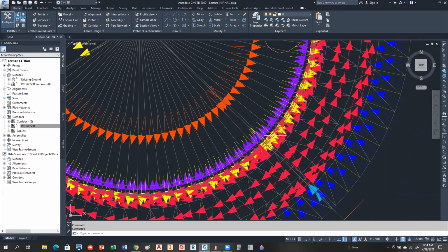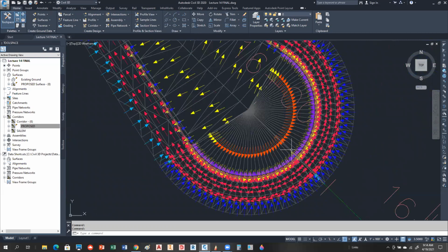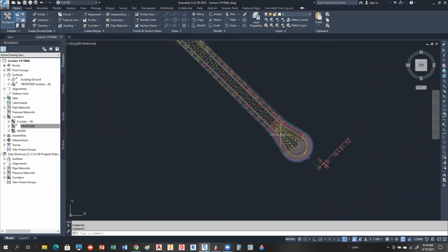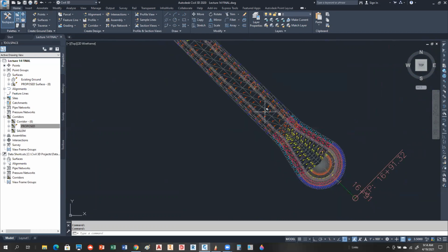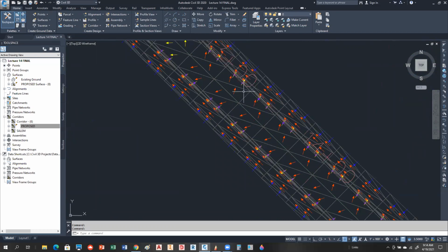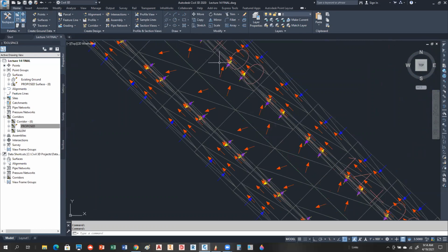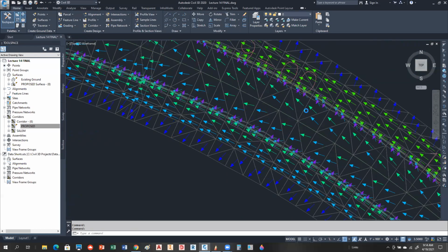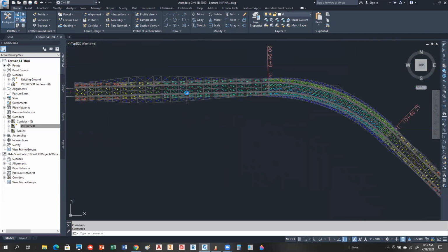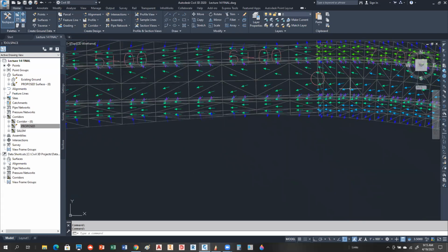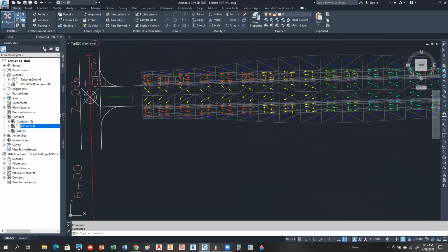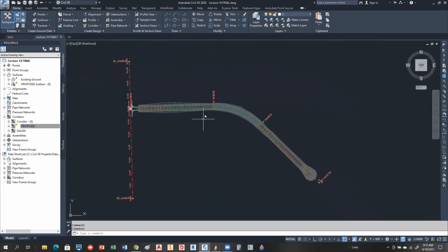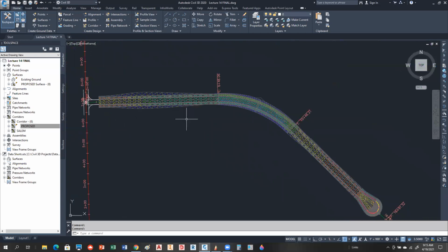If you've ever driven in cul-de-sacs, you'll notice there's usually a catch basin at the end of it, unless it's just draining a different direction. So, if that thing's high up, it might be draining out. But notice the rest of this thing is pretty much primarily just going downhill. So it's hitting that curb and gutter, and then it's just flowing. I don't think we have any low spots developing because this road's just going all the way down. So that's a very cool tool when you're dealing with drainage, particularly on your intersections. Any questions on that?